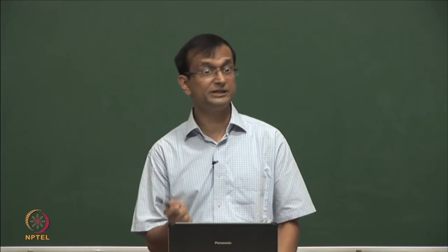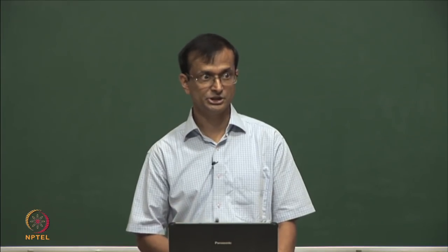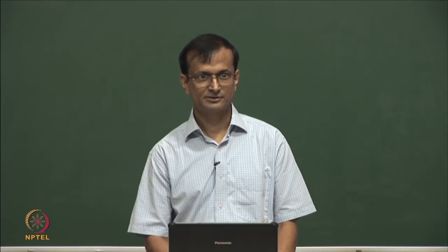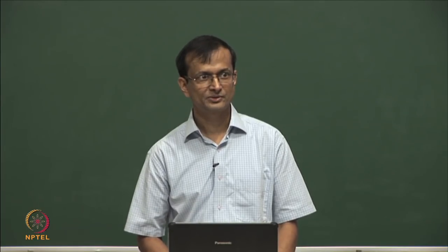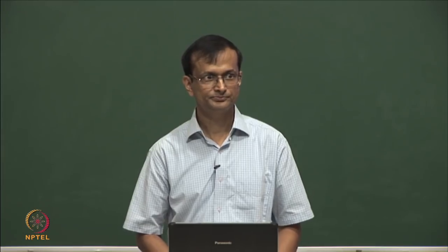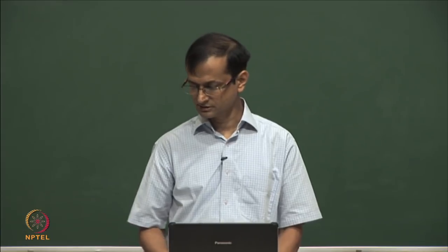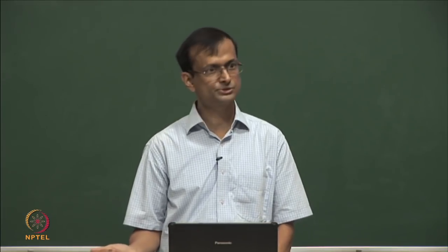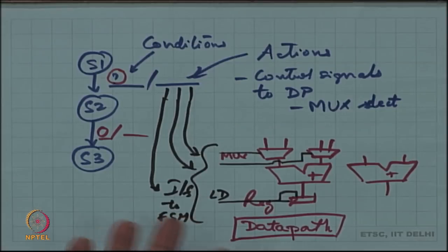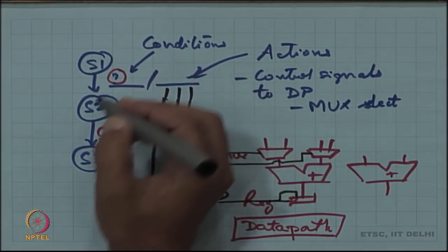Yet it is an incomplete FSM if I don't specify a condition. Can't we have a separate status signal, like in a processor, a status flag that is set when the addition is complete? Okay, what status signal? This circuit is so simple that you should be able to complete it. What status signal do I rely on? The rising edge of the clock. On the rising edge of the clock, right. But do we put the clock here as a condition?